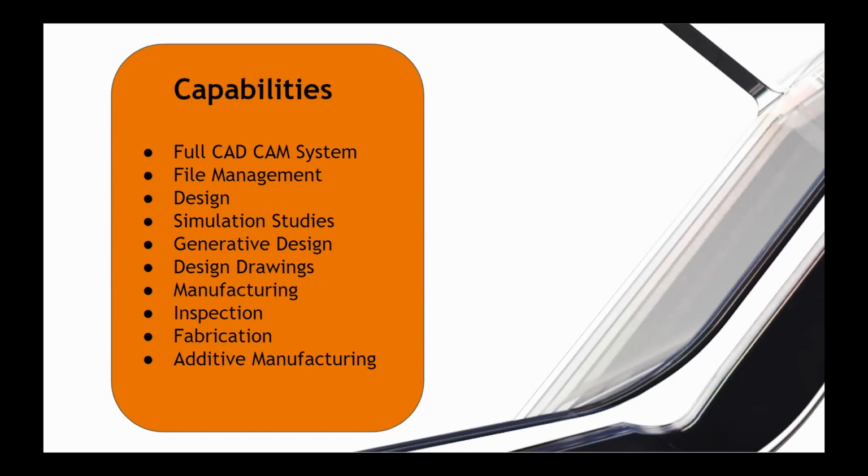And then as far as manufacturing goes, Fusion 360 has a lot of CNC manufacturing capabilities, meaning everything from turning, 2-axis, multi-positional, to 3-axis milling, 4th-axis milling, and also some 5-axis milling. Again, I want to make sure you understand that this is not to say that it's on the same level as something like PowerMill or something like that. It is not. However, where Fusion 360 really shines is being more of an assist to these other software.